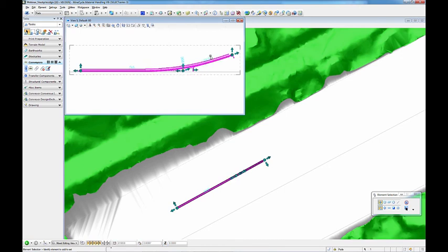A profile view allows optimization of the belt properties. Changes to material, belt width and speed can very quickly be visually analyzed to check the primary design is going to function as intended.